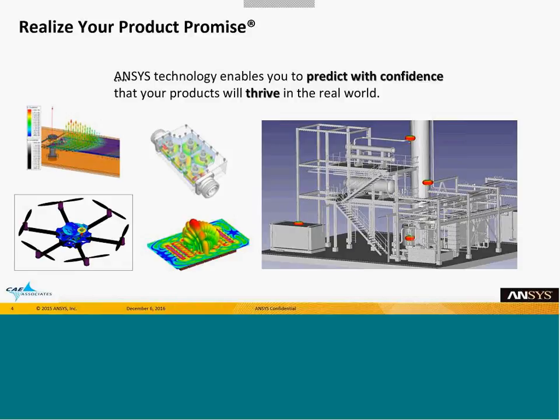So one of the simplest forms is, if you open up any electronics, you're going to see a printed circuit board. And one of the important components of this is to take a look at the via. The signal comes in through the via and it's transported along the microstrip trace, whether it's on the board or embedded in between boards. So what you see here in the colored plot, red is the hottest, blue being hardly any field. This is a plot of the electric field strength.